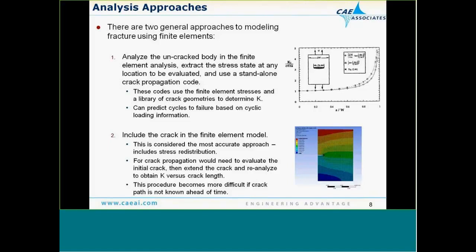So what you do is use your finite element analysis to grab the stress in that region, and then you push those stresses into these codes and then calculate what the stress intensity factors would be. Or the more difficult way is if you build the crack directly in your finite element model and then calculate the stress intensity factor. And that's what we're going to talk about today, because that's some of the new features that are in Workbench. Keep in mind, it's a challenge to do this.